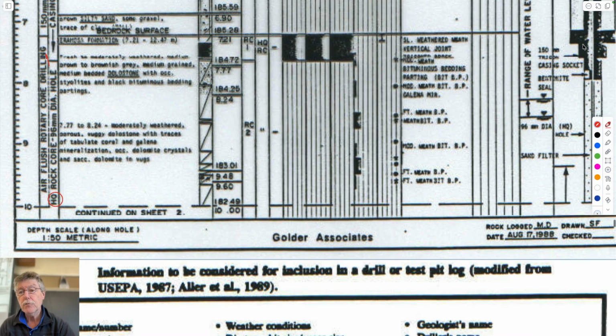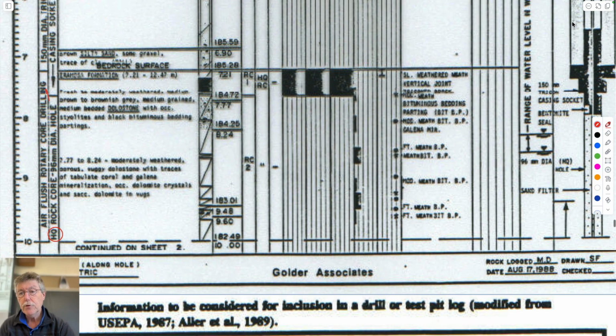So this is a picture of the wellbore. This is the wellbore going down at larger diameter to the rock. This is the casing that, if it's cased, perhaps not cased into the rock. This is where the casing that goes up to the surface is being grouted in to give a good hydraulic connection, no flow in other words, between what's happening up here and what's going on down here.